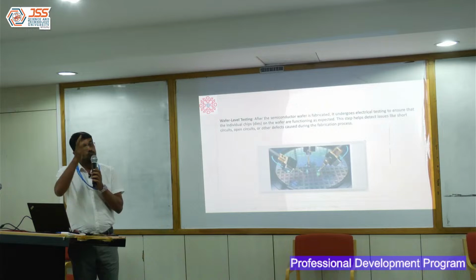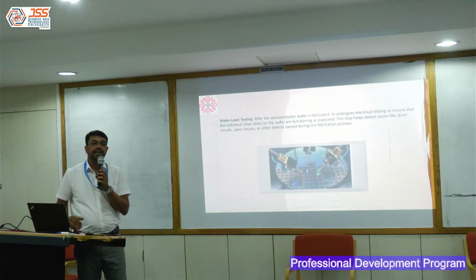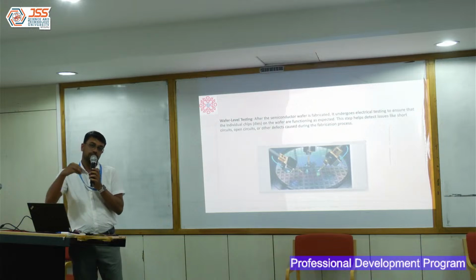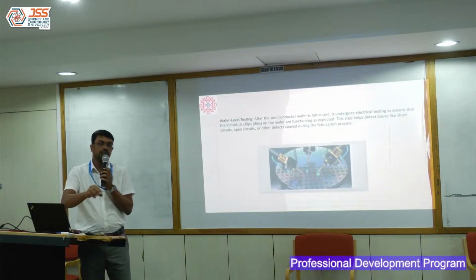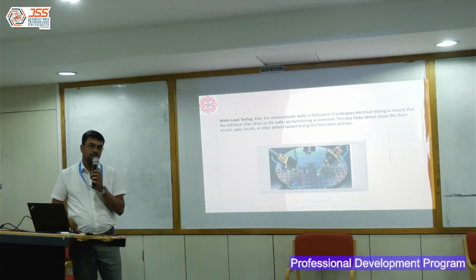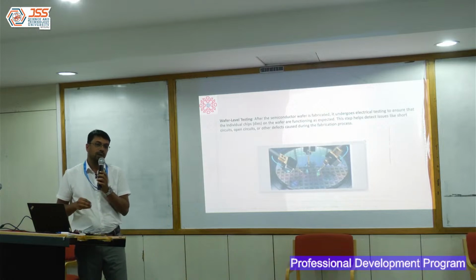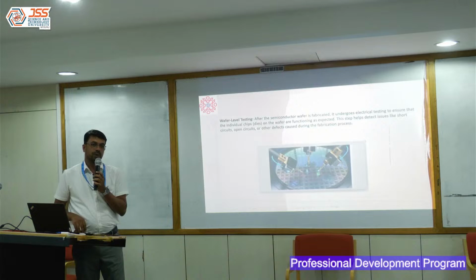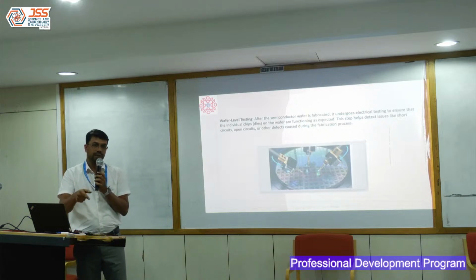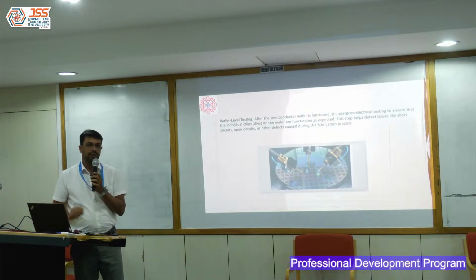If you go back to an older, very proven technology node, say 60 nanometer, yield can be as good as 80 or 90%. With the newer technology node, you are at a risk of this yield. So the fab also gives you certain discounts if you move to a newer technology node. Typically for our test chips, we can take that risk because they give certain discounts, as they are also in an experimental or learning phase. We are also in a learning phase. It benefits both.